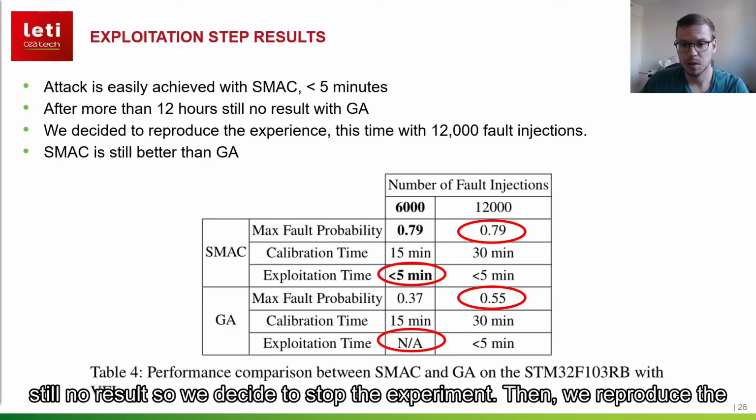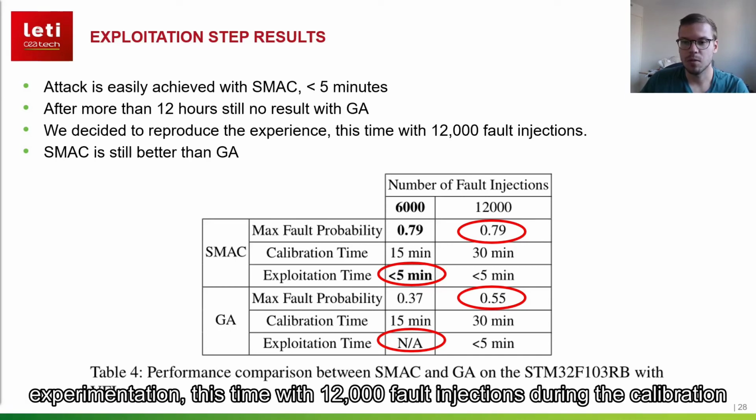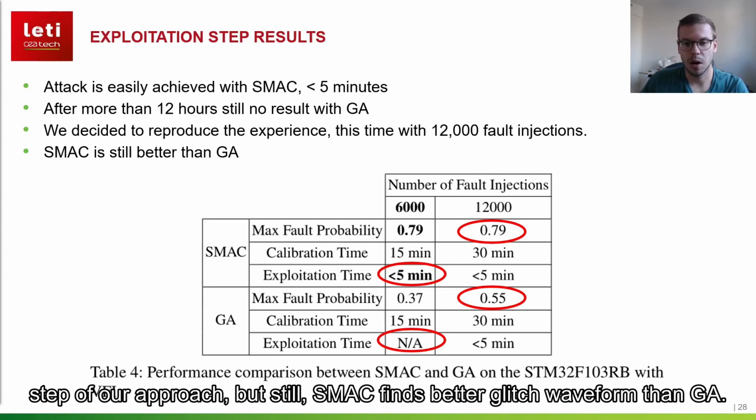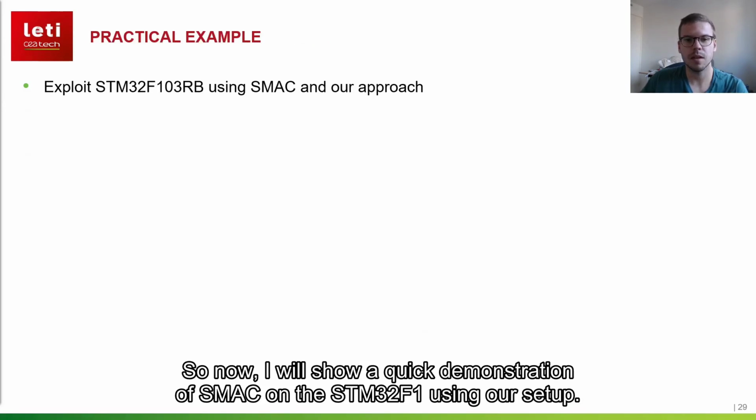Then we reproduce the experimentation, this time with 12,000 fault injections during the calibration step of our approach. But still, SMAC finds better glitch waveform than genetic algorithm. So now I will show a quick demonstration of SMAC on the STM32F1 using our setup.